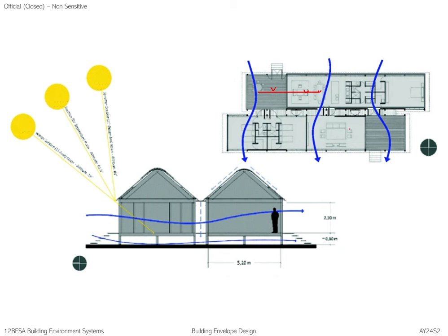Okay. So the way that cross ventilation is catered for, you notice that for the toilet areas, it doesn't allow cross ventilation and the air to be brought into the bedroom. It's actually brought into an open space, a veranda space. Whereas in this case, it's living dining to living dining, so not much of an issue to have cross ventilation. This one as well, veranda space to the bedrooms, and you have the toilets in the middle, ventilated directly to the outside.